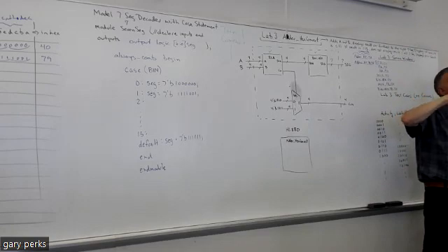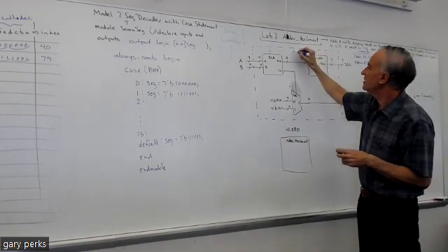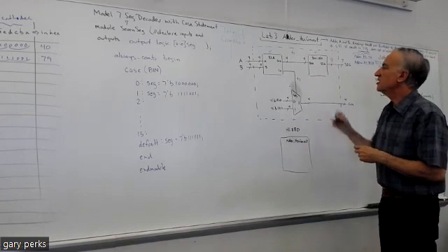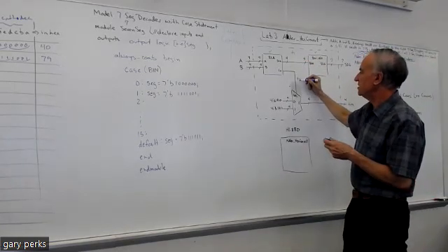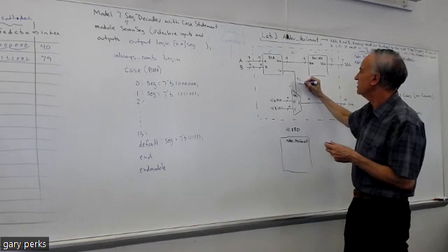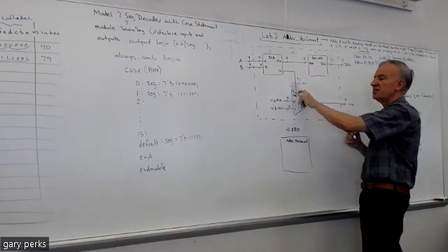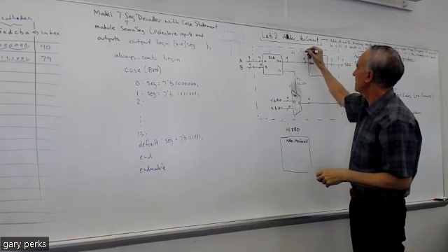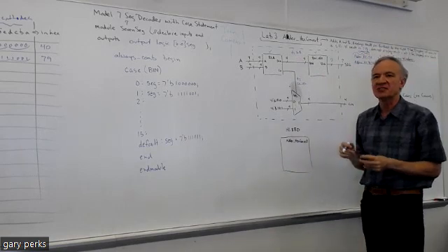Internal signals. Yeah, internal signals. So you need like a T1 here and a T2 or whatever you want to call them. To be more descriptive, instead of using T2 here, you could do C0 select, because this is connecting carry out of the RCA to the select of this mux. And you could call this S underscore B or some underscore bin or something, you can be more descriptive.